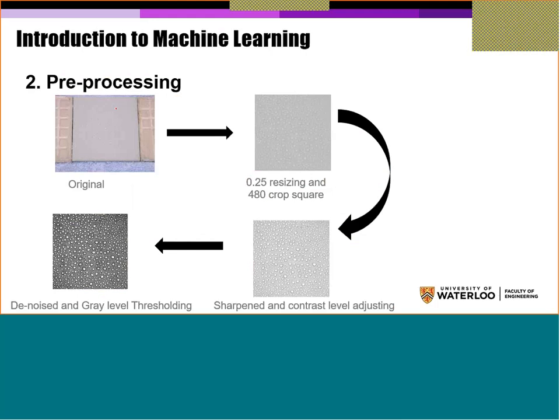So this is an original image. We took it for the surface of ceramic tiles covered with silicone rubber material. Now this is the original signal, which we call here a two-dimensional signal. The signals that I showed you, partial discharge, are called one-dimensional signals because you have only the x-axis, the t. Here, this has an x and y. We call it a two-dimensional signal. So if we look here, the first thing we want to do is try to crop this and resize it so it becomes much better. Those tiny dots are water droplets, and I will talk about this problem specifically in the coming slides.